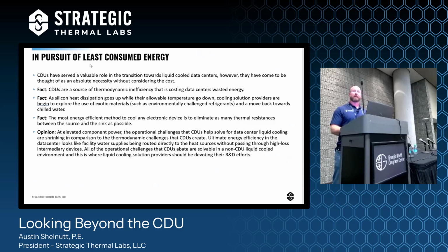One question I had was another trend that we see is in cold plates, that the feature sizes are often dropping from, say, like 300 microns to 100 microns. Given the increased filtration requirements of smaller feature sizes, do you see any challenges of having the CDU out of the loop and facility water going directly into these, let's say, more sensitive environments?